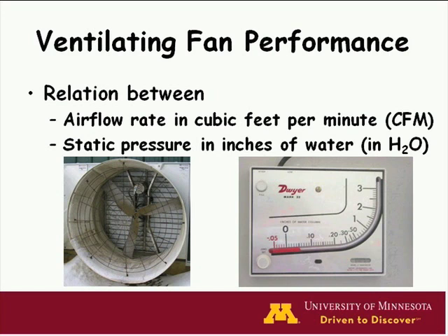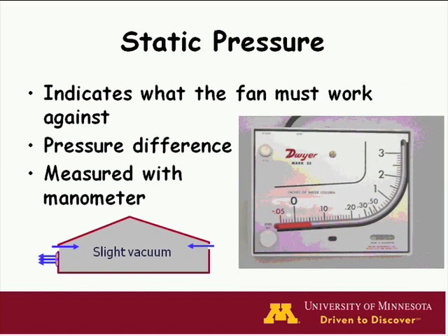This information on fan performance is measured by conducting standardized tests. These tests measure the airflow at different static pressures, and for agricultural fans, the static pressures range from 0.05 to 0.3 inches of water. Now, the static pressure indicates, again, what the fan must work against while it's providing this airflow. And the most common static pressure measurement that we look at for mechanically ventilated buildings is between inside and outside.